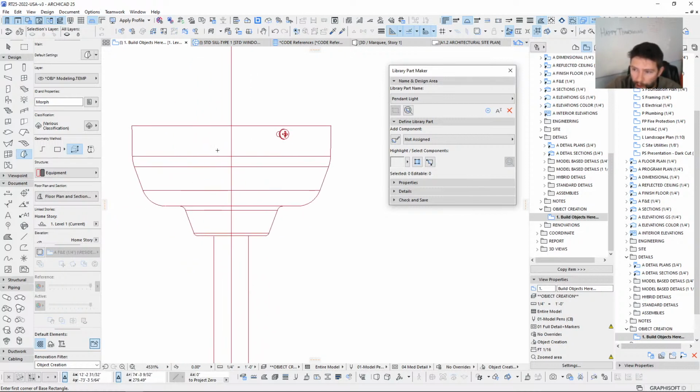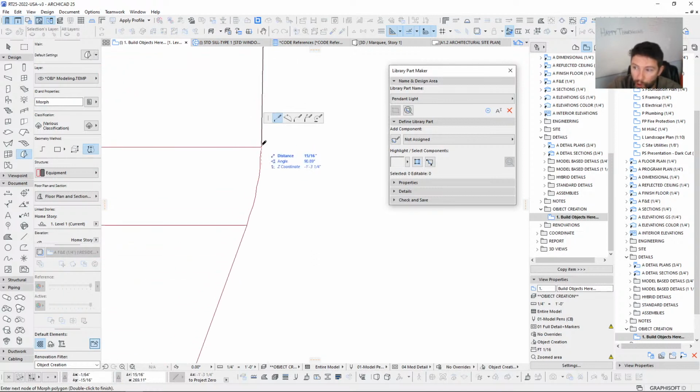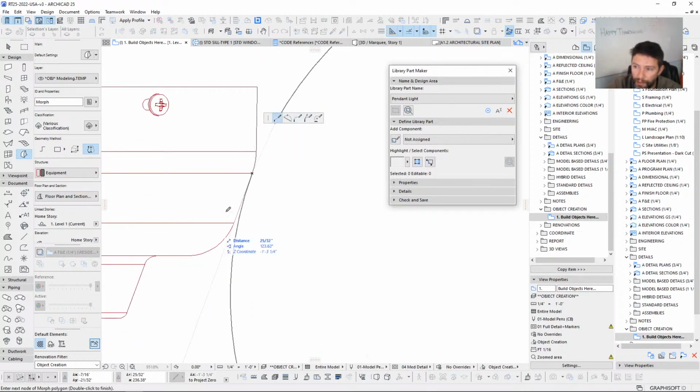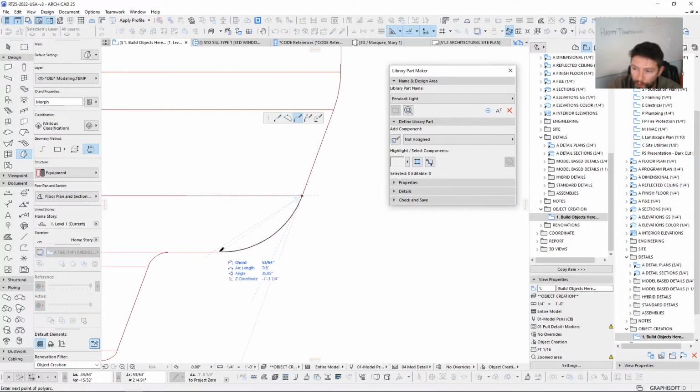But okay, let's go ahead and start with our morph tool. We are going to be using the revolved geometry here. So I'm going to start from my center line, bring this straight out, and simply trace over this here. If we wanted, we can use some different methods here. The tangential method, is that how you say that? It is always a good one for getting these to look nice and curved as we go through. I find that's usually the easiest one when I have a reference like this.